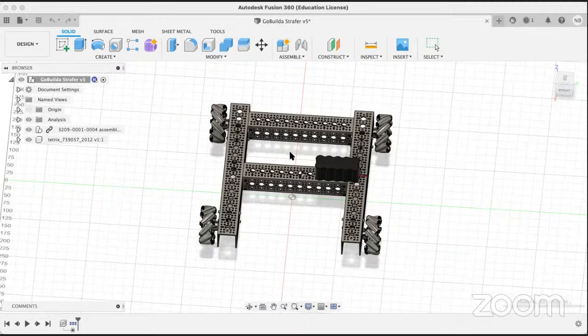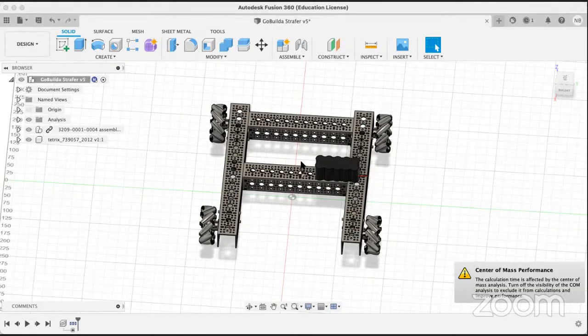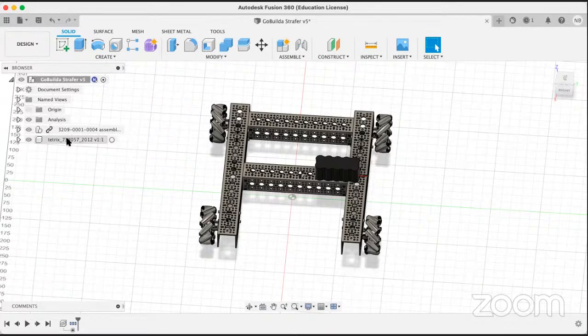Then what you would want to do is, in the parts section, import that part, cut that section, create a new part, and then import it to your model. Okay. So typically that's how you would want to do this, and not make that change here in the main robot. The main robot should have all parts that are linked to some part section that others can also use.